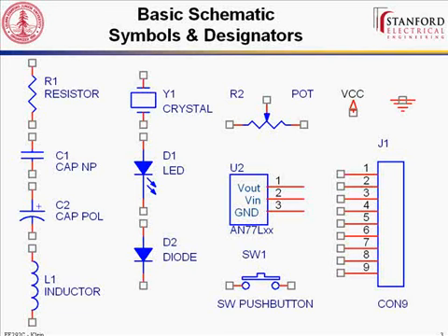So below that, I have this AN77L something part. This is an integrated circuit. And so all integrated circuits, all the chips, have a designator of U. Now, transistors by themselves have different designators, but an IC actually has a designator of U. So this is one part, for example, that's a voltage regulator. It's got 3 terminals, an output, an input, and a ground. So it takes in some arbitrary voltage, and it converts it to some other arbitrary voltage depending upon the part number.